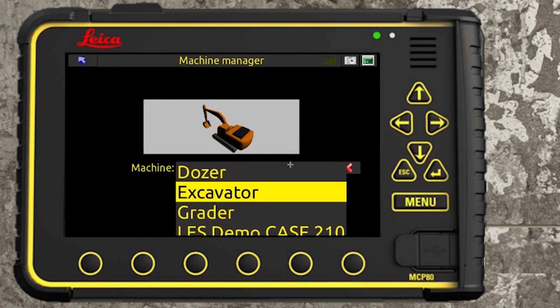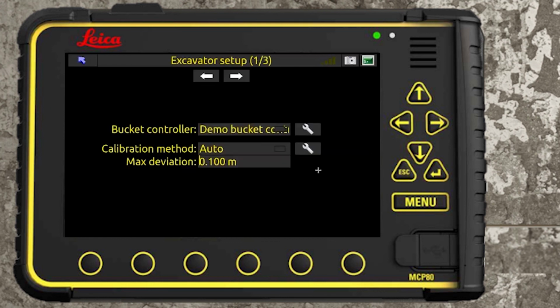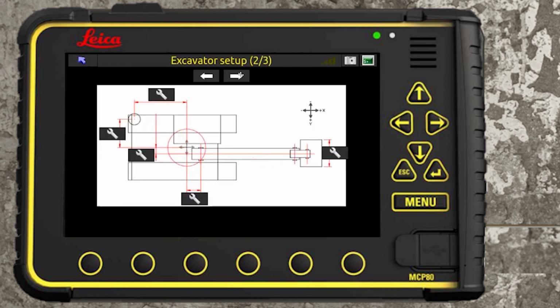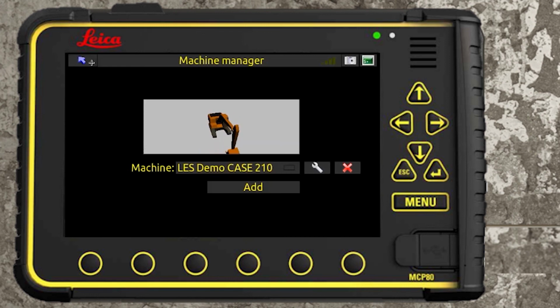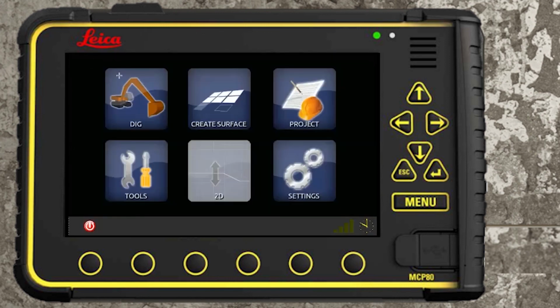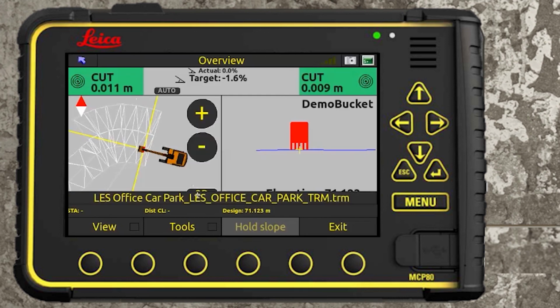If we drop that back to the demo case, which is calibrated, I'll just show you real quick. If you go into your spanner, scroll across, I have my settings here. So my GPS X position, Y, I have the roll length, pitch length, I have the boom length, stick length. If they were all at 0, that's where you'd see. You wouldn't see it up in your panel. You wouldn't have a machine or a boom or a dipper.